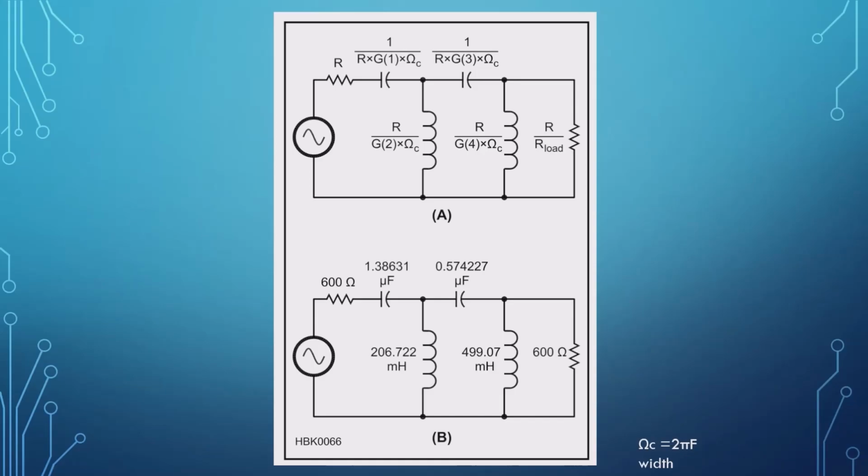Hey Jim, that's a lot of work. Yes, sir. Just a quick question. On the system impedance, what's driving that in our application for this project? That's normally driven off of, let's say, a mixer or an amplifier. Your amplifier might have a different impedance, and you need to drop it down to like 50 ohms, or it depends on what you normally want to deal with.